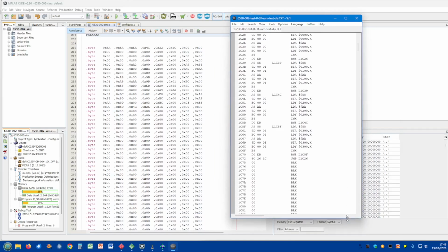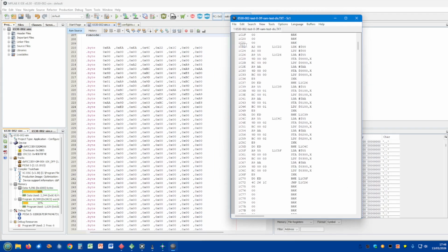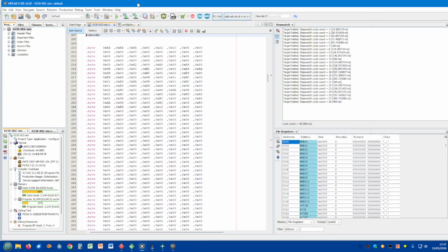Used this before to test the memory. So it just comes in the same place as the KIM ROM normally comes in. And this is just loading FF and AA in and out of data all the time. This is basically like a RAM test, and tells which bits are on or off. I'm just using it as a piece of code to run, and we'll have that running instead of the actual KIM program to see if it's anything to do with the software.